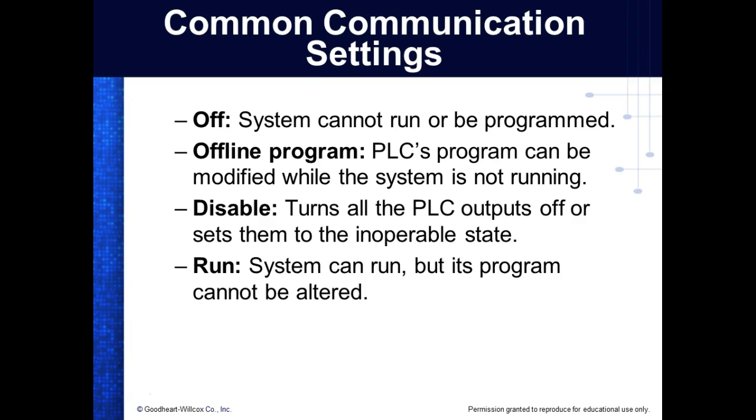Common communication settings off. Most of your PLCs are only off when you unplug them. Then we can put the PLC into what we call offline mode. So offline, if you've got your computer offline, your PLC offline, it means it's just not running a program.